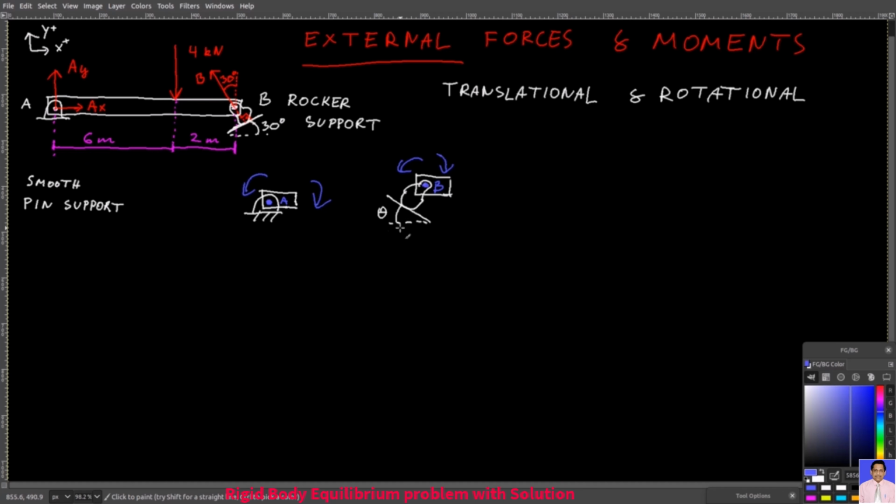Of course, in reality, there is always a bit of internal friction between the pins and the rest of the structure when you rotate that structure about the pins, but this is not real resistance. You cannot count on it in order to stabilize a structural element. This internal friction is too small for that, and it's not even supposed to be big. It might be necessary for you to allow this rotation.